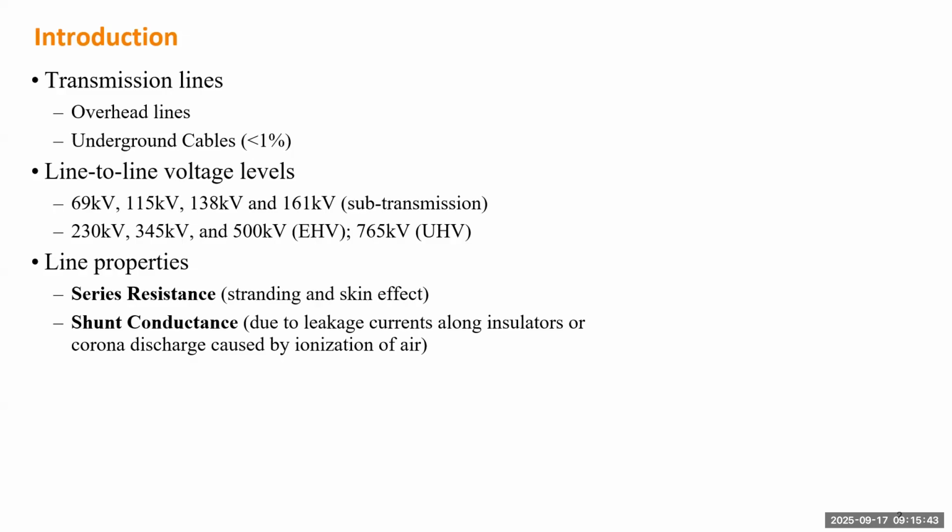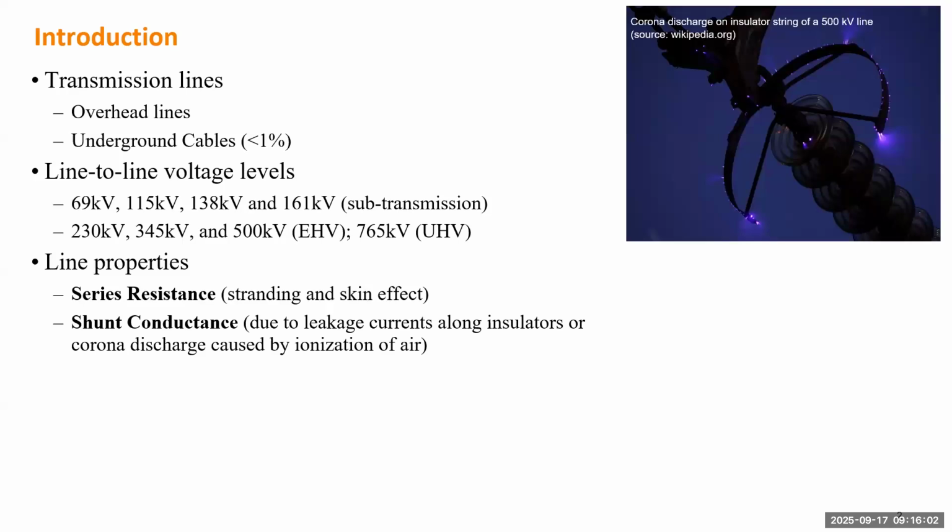That's called short circuiting. But because you operate the line at a very high voltage, that can make part of the air surrounding the insulated conductor conduct current, which means you can lose energy because you operate this very high voltage line. One picture shown here is called the corona effect.